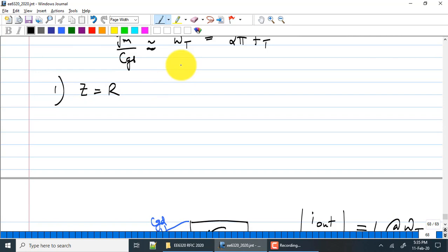But that imaginary part can easily be cancelled by adding an inductance or a capacitance. Once you find that a circuit has an imaginary part and a real part of 50 ohms, the easiest thing is this. We had the same problem when we added a shunt resistance of 50 ohms at the gate. It still had a capacitance. What did we do? We solved that by building a narrow band LNA where the capacitance was tuned out by the inductance. That is very easy to do. At the end of the day, we would much prefer to build a narrow band LNA which works really well and has very low noise figure, compared to a wide band LNA which is not good enough.